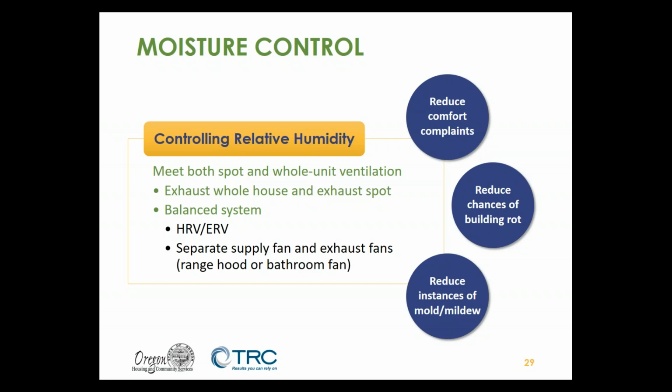Let's talk about moisture control. So here's the other big reason that your multifamily buildings will need ventilation: moisture control. So reduce comfort complaints, reduce the chances of building rot, and reduce instances of mold and mildew. So humidity on the inside has a big impact on our comfort indoors, right? Different temperatures feel differently with the various relative humidity. You get really low humidity, you get those chapped lips, you start feeling dry in your mouth. That's a nasty discomfort that can really impact the way that you feel about your day and your life.